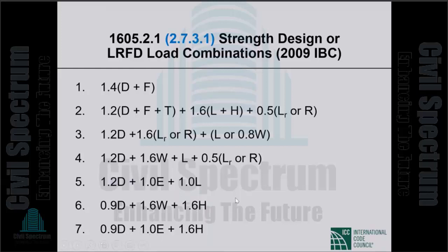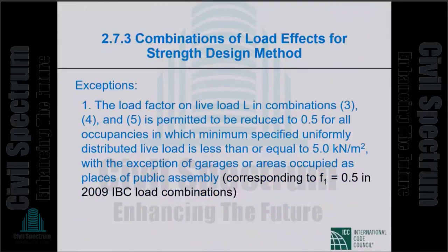Okay, so we call them load combinations. They are actually combinations of load effects. That's very, very important. You cannot combine loads. Dead loads act vertically down. Live loads act vertically down. Wind loads act sideways. How do you combine? You cannot combine. We never have combined loads.